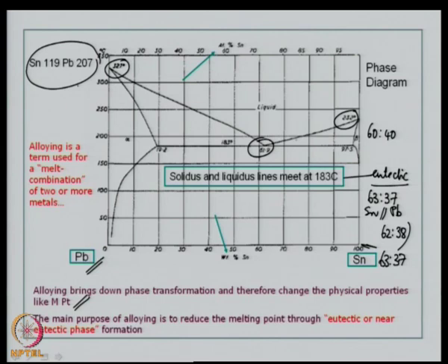So, one needs to understand the tin lead phase diagram, because if you are choosing alloys of tin lead in electronics other than 63/37, you need to know the melting points, which will definitely be higher than 183 for all other systems. Okay. So, here if you look at